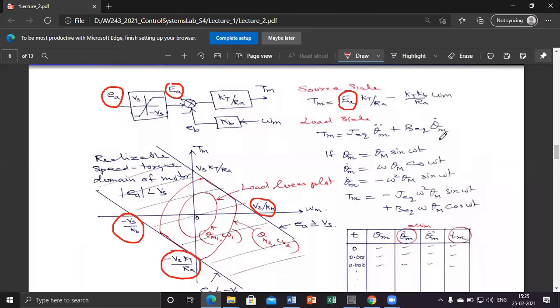One typical example is many of the launch vehicle nozzles. We would like to deflect with a plus or minus 5 degree amplitude and a frequency corresponding to some 5 hertz. And normally, even though the amplitude is 5 degrees and the frequency of operation is 5 hertz, there is a correlation between them.